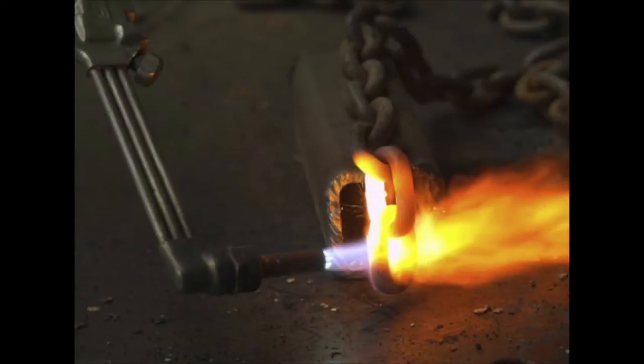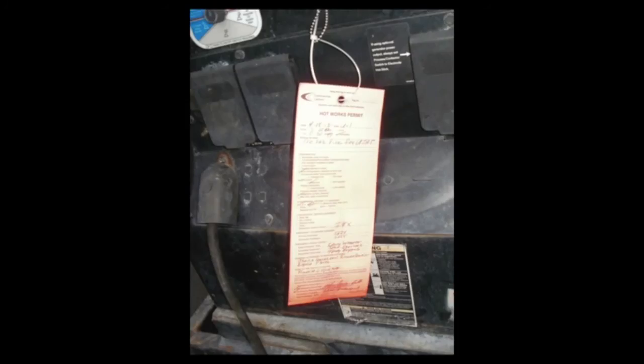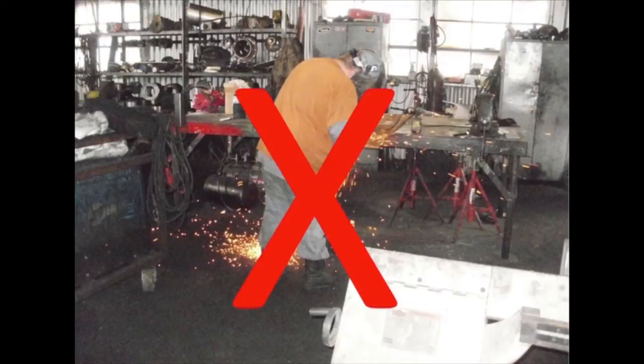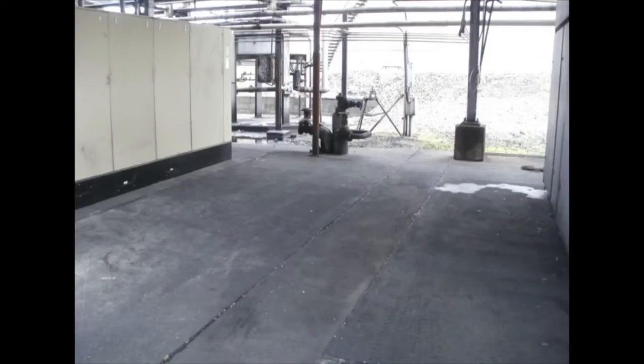Hot work is the name given to any task that produces heat. This includes welding, cutting, grinding, or use of a torch to heat or thaw pipes. At Continental Carbon, all hot work requires a permit. The only exception is when the work is conducted inside a shop or specially designated area that is free from combustible material. That is, items that will burn, such as wood, paper, solvents, fuels, etc. If hot work is to be conducted anywhere other than this special area, a permit is mandatory.